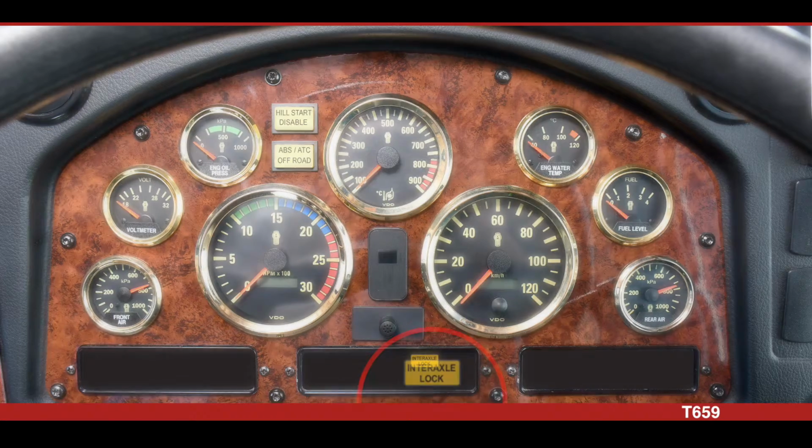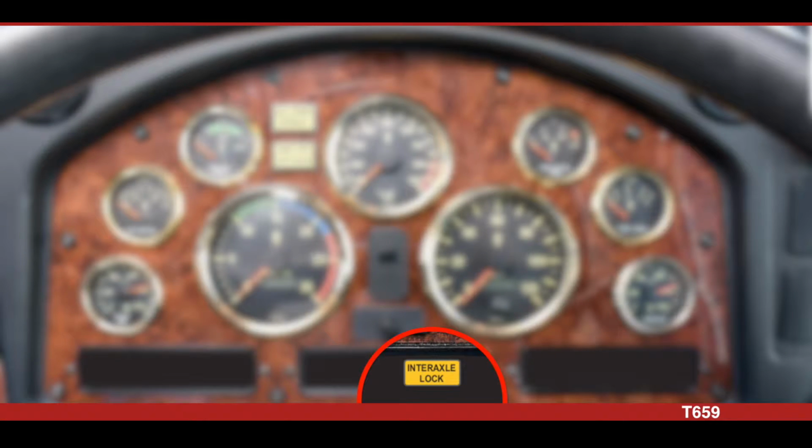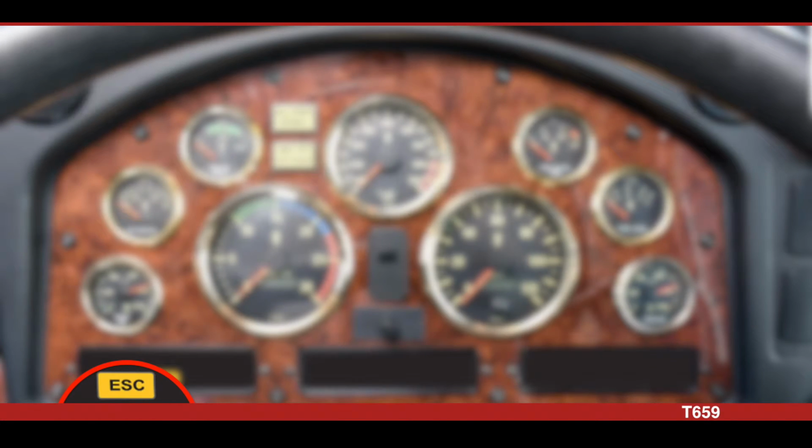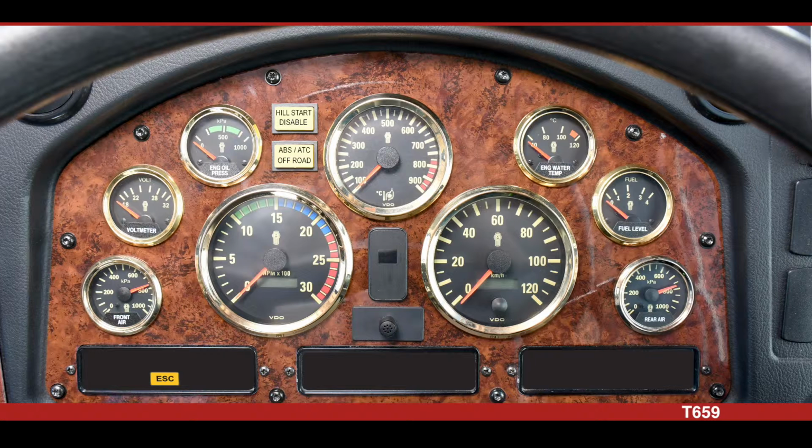The interaxle lock will illuminate when the interaxle or power divider is activated. The ESC light will illuminate briefly and then go out when the ignition is first turned on. The ESC or traction control warning lamp will illuminate whenever the automatic traction control ATC system detects drive wheel spin. The lamp will remain illuminated as long as wheel spin is detected and the ATC system is applying the drive brakes or reducing engine torque.